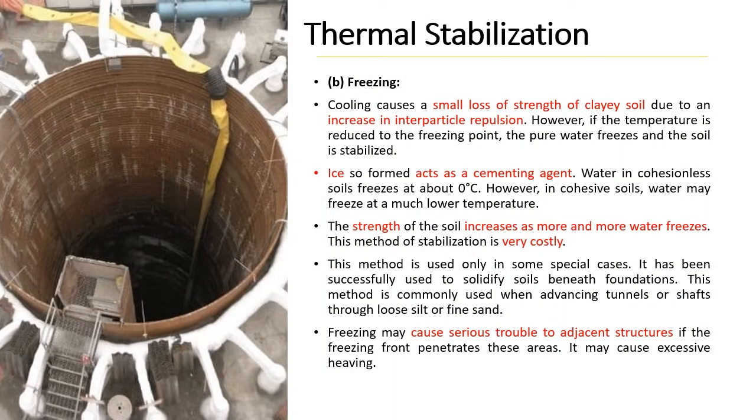Under thermal stabilization techniques, freezing of soil can also be done. Cooling causes a small loss of strength of clay soil due to an increase in interparticle repulsion. However, if the temperature is reduced to the freezing point, the pure water freezes and the soil is stabilized. Ice acts as cementing agent.